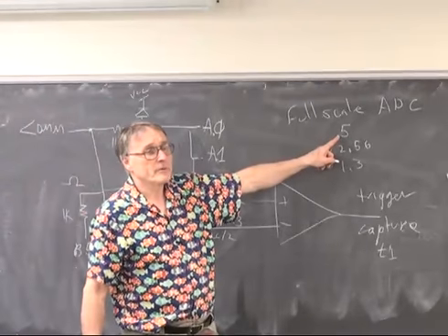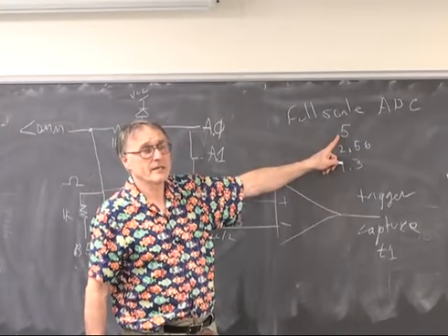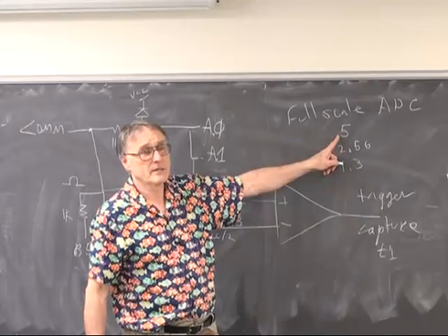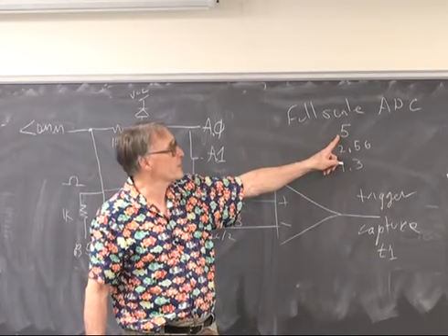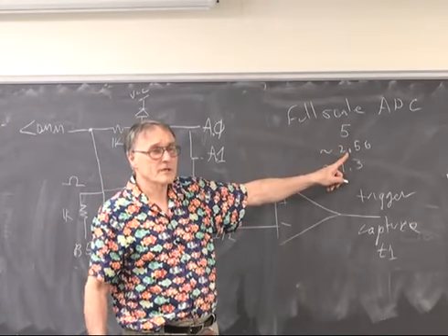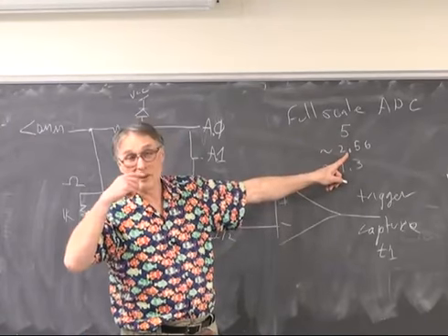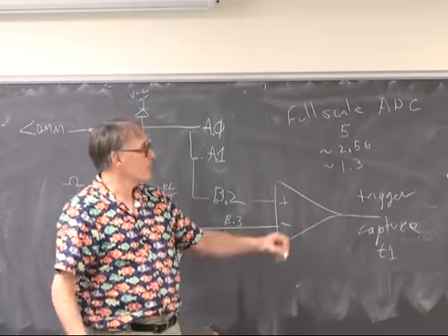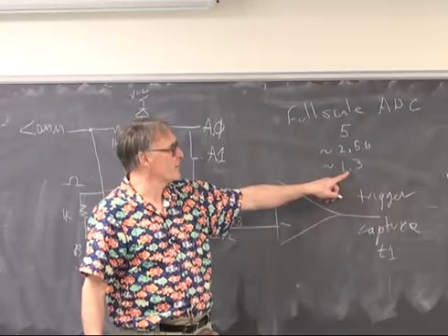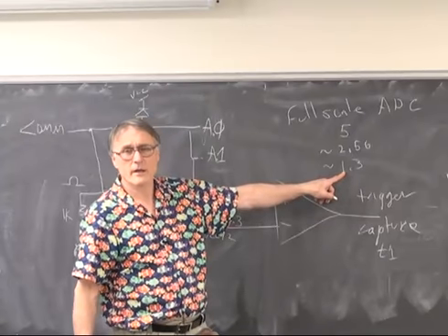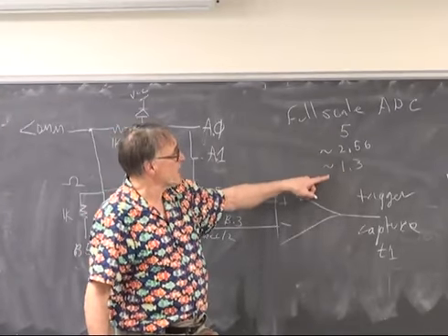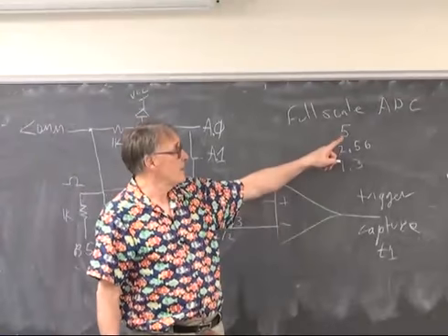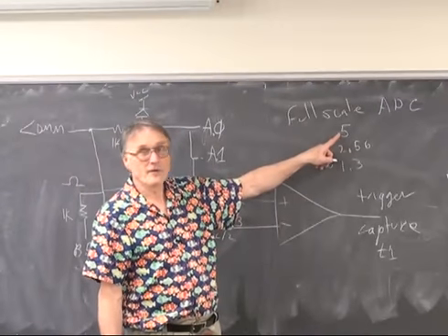The 5 is accurate within a % or so because that's AVCC. It comes right off a voltage regulator. The 2.56 comes off of some internal voltage reference, which is good within about 10%. You have to measure voltages within 2%. Therefore, you will have to calibrate it, most likely. And the 1.3 is probably about 5%, but you better check that. So you're going to choose the full scale. If the voltage is big, if it's greater than 2.56, you better choose 5.